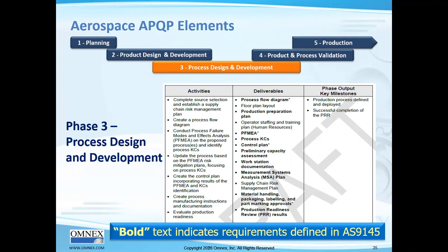Now, a couple of things that are not as big in aerospace as they are in automotive, that you will have to do, are your MSA, your measurement system analysis, a big part of that being your gauge R&R, right? We don't do a lot of MSA in aerospace. We all do calibration, but a lot of our tolerances are so tight on the drawing that we don't really do a capability study, because in the past, as long as every dimension on the prints was within the tolerance, it's going to fit, it's going to do what it's supposed to, and the customer's happy. So there are a few things that you're probably not doing, or not doing as well as it needs to be done, for AS9145. Those are things you have to take into account.